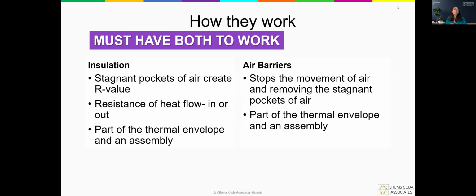When we talk about the thermal envelope, a lot of times people think about insulation, and insulation is absolutely one of the items that are a part of that assembly, but the insulation really cannot work on its own. It's got to have that air barrier component with it to make it all function together.